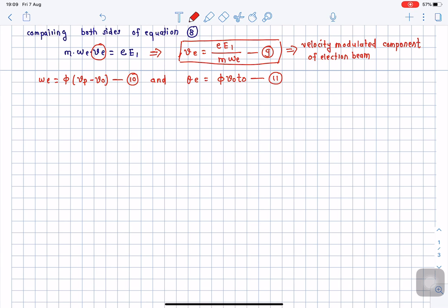So the convection current over here, I will directly write the equation for the convection current in traveling wave tube. See why it is called a convection current, because this current is not a direct DC electric current, but this current is developed because of the space charge effect which is generated by the continuous interaction of axial electric field with a beam of electrons. And this current which gets generated and which is responsible for the amplification process in a traveling wave tube, we call it a convection current.